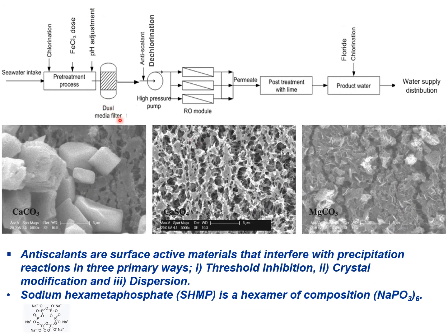After pretreatment with the dual media filter and just before the reverse osmosis, you need to go through anti-scalant dosing. So what is anti-scalant? We have seawater and we extract water using reverse osmosis, which means the concentration of calcium, magnesium, and silica, the very dominant inorganic scaling compounds, increases. For example with calcium carbonate, because pure water is extracted, the concentration of calcium and CO3 increases,